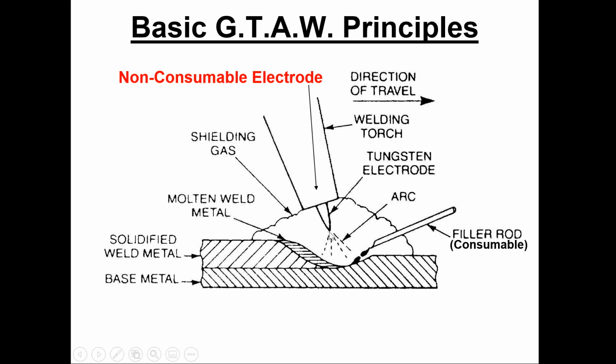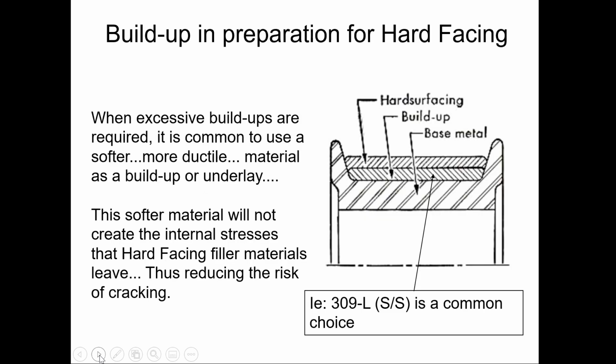Quick word here for safety. Never, ever sharpen both ends of a tungsten for a bunch of reasons. First reason, when you're sharpening it, you shouldn't be holding on to a sharp end. There shouldn't be two sharp ends. Second reason, how do you know what kind of tungsten it is now? You've taken the little band of color off of it, and now it turns into a big problem. We don't know what it is. It should just get tossed in the trash.